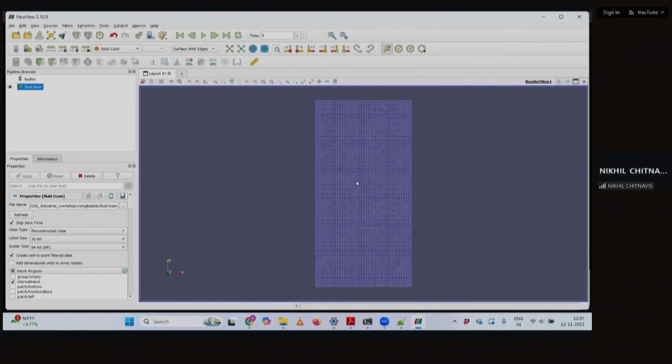So in case of this surface or interface capturing application, it is advised to give a very fine mesh to properly capture the interface, if you are not changing the mesh using adaptive mesh refinement or any other technique. Because our mesh is static, everywhere we have defined this fine mesh.